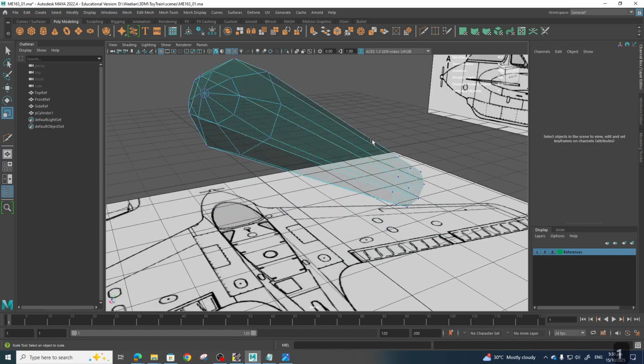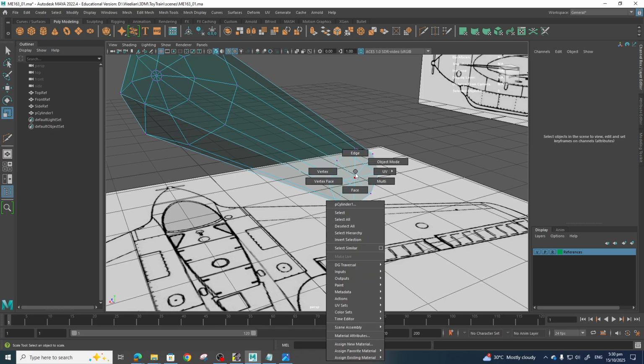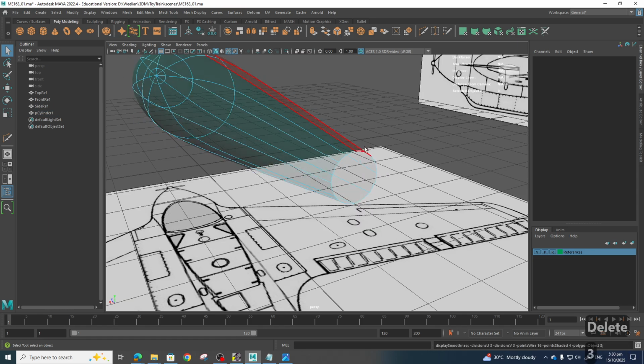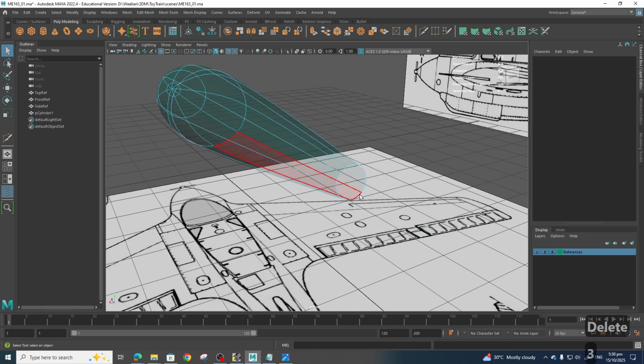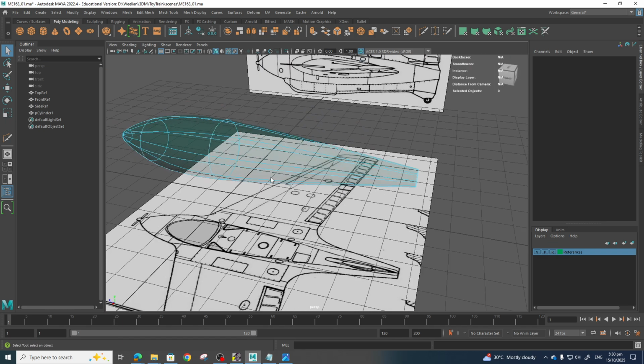What you want to do also is that you want to get rid of the faces in the back here. So I want to use vertex first. Select the vertex, the center vertex here, holding down control, right mouse click to faces, then delete. So that when I subdivide this, the central vertex will not collapse into a dot here. So we actually have a hole over here.